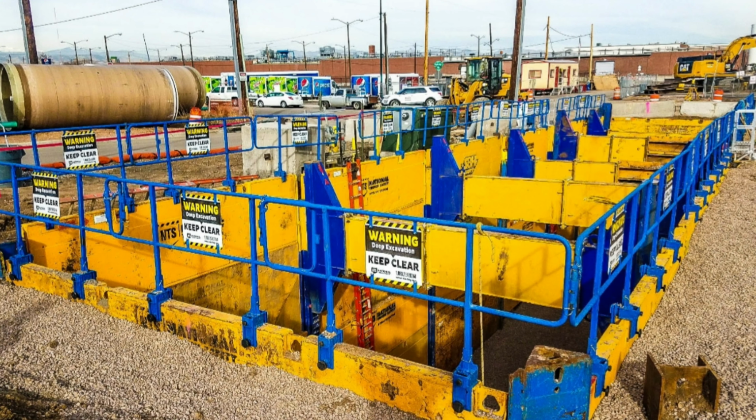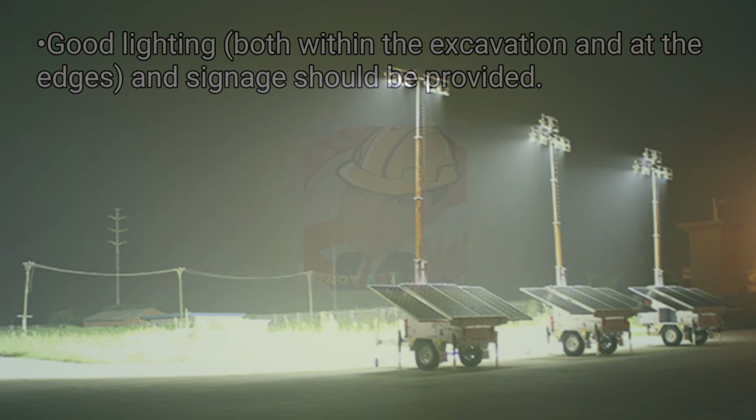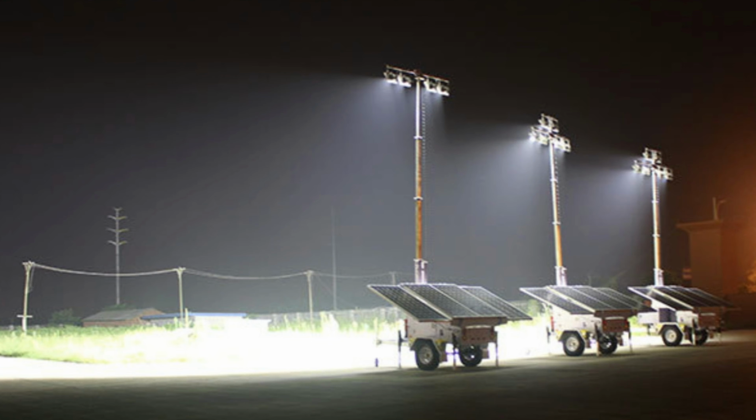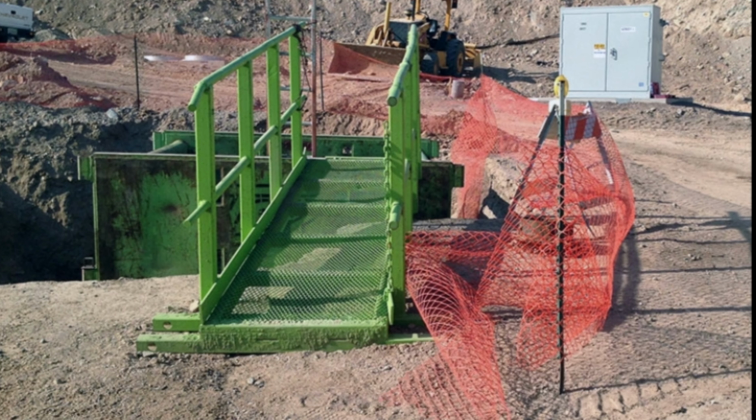Prevention of falls. Preventing people from falling into the excavation can be achieved by use of barriers. Barriers should consist of guardrails, as for a scaffold work platform, to prevent people falling in, and toe boards to prevent objects being kicked down into the excavation. Good lighting, both within the excavation and at the edges, and signage should be provided. Long excavations should be provided with crossing points, bridges, that should be similarly guarded with barriers and toe boards.